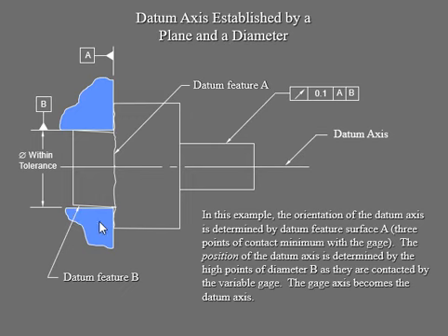They are perpendicular to each other. So your gauge axis, which is this guy, is going to be your datum axis. And of course, in the diagram here, there's a note that this axis is your datum axis because of these two planes gauging it. And our circular runout is 0.1 with datums A and B. All right.